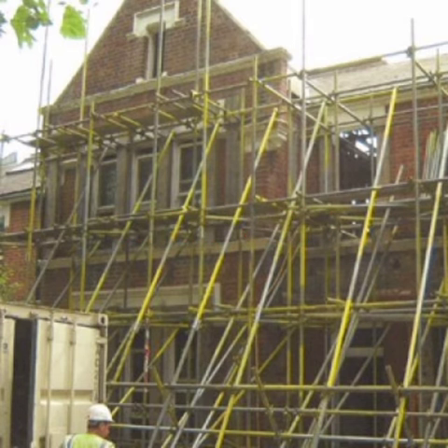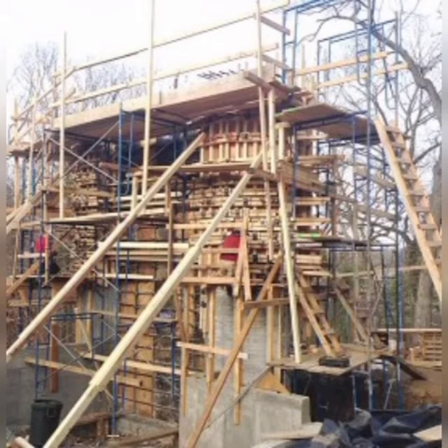There are three types of shoring. Racking shore. In this method, inclined members known as rackers are used to give lateral support to the walls. For shoring, timber and steel tubes are used. When timber is used, it is coated with preservatives to protect against the weather.